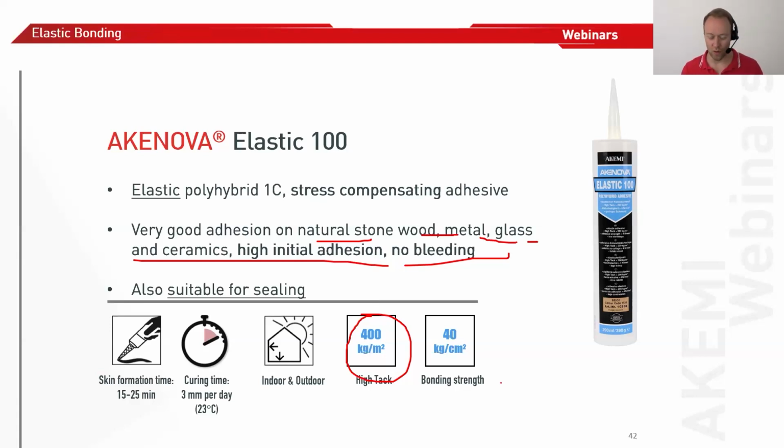And of course, you also have a lot of bonding strength later on. Regarding application, it's usable for 15 to 25 minutes. Then you have this skin formation time, when it starts to get solid. It cures overnight, of course, but then it gets solid. So you should move the parts before that time.